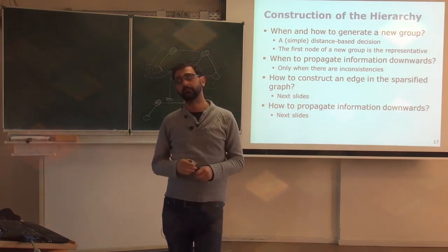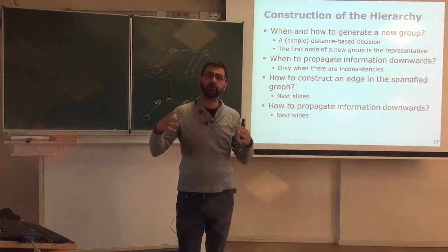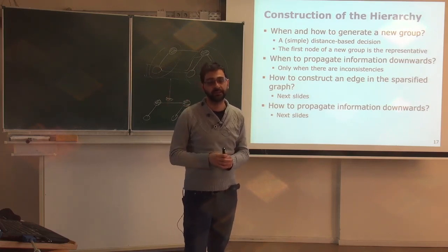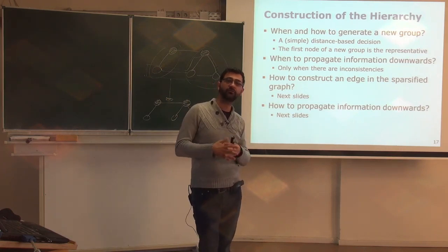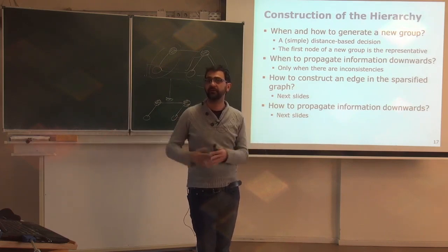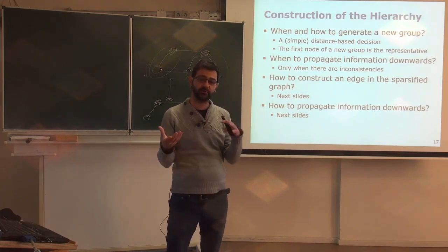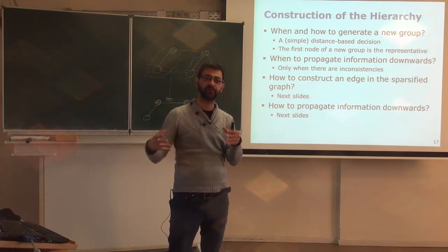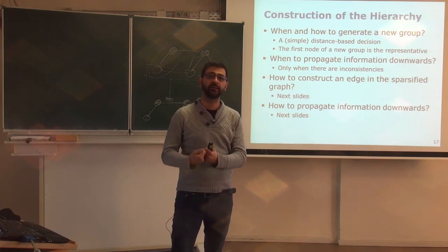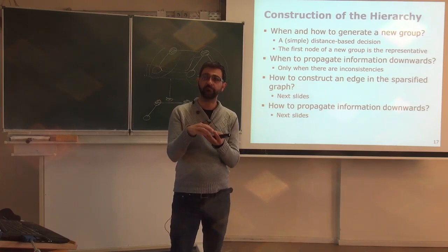One idea is that once in a while, we rebuild the whole hierarchy again. Since we do it only once in a while, it's not so computationally expensive; it's amortized over the life of the robot operation. This allows us to keep the hierarchy in place so that we do not accumulate too much approximation error, and we don't defeat the whole idea that things which are close by will stay close by.